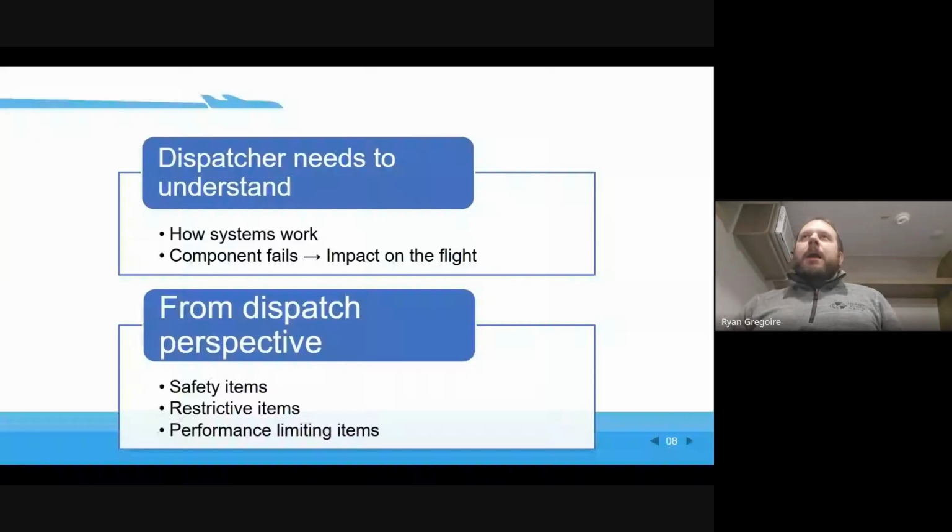You might say, why do I need to know that there are 3 hydraulic systems with 2 pumps per system and the emergency backup system is the 3B pump? Until you get an aircraft that has a deferred 3B pump that you can't fly, and you're like, well, if I have 5 other hydraulic pumps, why do I care if the 3B pump is not operational?